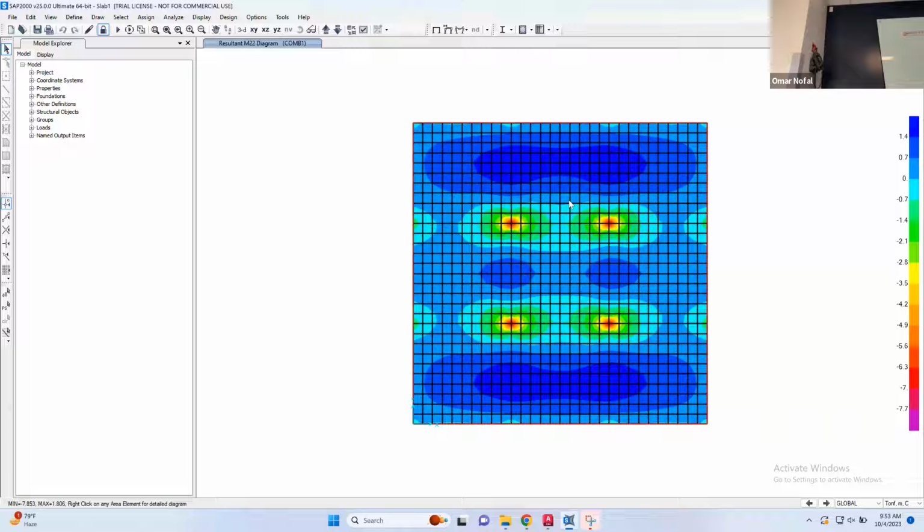So first, we do gravity analysis, a 2D model, get the beams, the slabs, and also initial sizes for the columns. Why am I saying initial sizes for the columns? Because right now I'm designing the columns only to take the gravity load, the vertical load. Once I have this initial size, I push the building with the seismic or the wind load, so I get what is the bending moment that this column has.